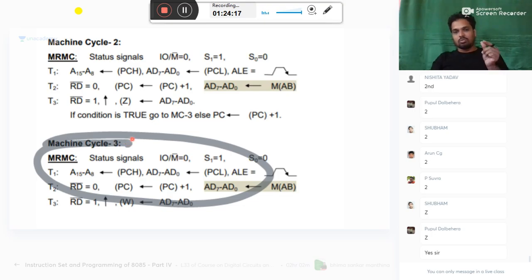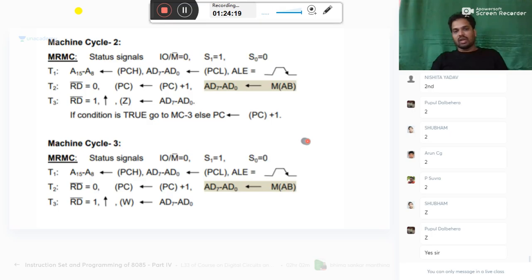So this is how you need to make an efficient design. Why wait to check the condition? Check the condition parallelly. Do it assuming it is right. Then no time is wasted for me. When the condition fails also, for checking the condition anyway, the time is required. At that time only I am doing this job. So now it is clear, even if the condition is not true, why waste one memory? It is not wasting, it is saving our time.